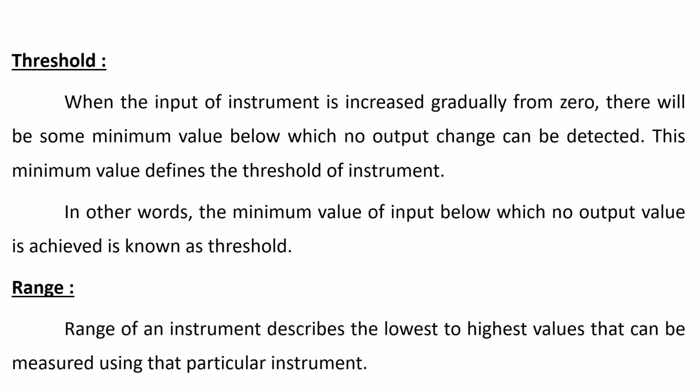Threshold: when the input of an instrument is increased gradually from zero, there will be some minimum value below which no output change can be detected. This minimum value defines the threshold of the instrument. In other words, the minimum value of input below which no output value is achieved is known as threshold.